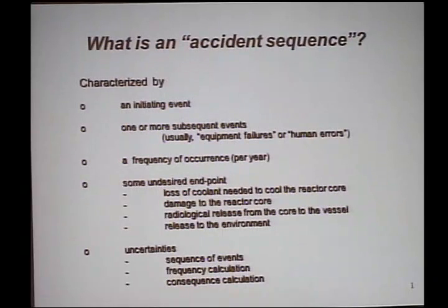which starts a sequence of events, and the reactor, remember, is designed so if you have a pump that jams, there's another pump that's supposed to be there to pick up the load or to perform the function or there's a valve that's supposed to close. So you have to think through an accident sequence in which, even though that's designed to work, it fails too. And then, okay, if it fails too, what next? Well, there's something else. It fails too. Almost all the accident sequences in the original report or in the PRAs that we look at have 3, 4, or 5 failures, not 1 or 2. There are very few with only 1 or 2 failures. In fact, I can't even think of one with 1 or 2.